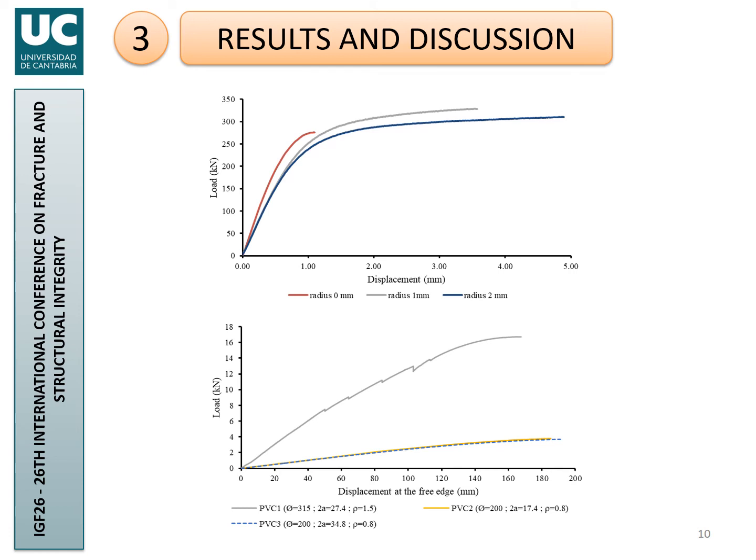less than a half of the apparent fracture toughness observed in 2 millimeter notch radius. Here you have 2 graphs. The one on the top corresponds to the fracture specimens with a clear notch effect. This is the cracked CNB specimen, and these are the notched ones. As long as you introduce higher and higher notch radii, you obtain much larger displacements on the test, so the behavior is more ductile, more non-linear.